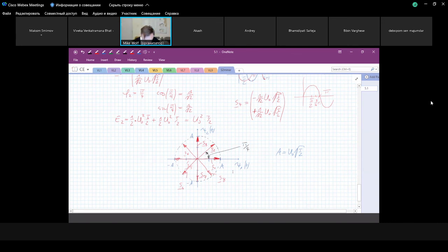This is, of course, the next topic, modulation schemes, but this is the signal space of 8 phase shifting. A modulation scheme where we shift the phase depending on the symbols to be transmitted. And we have 8 different levels for this phase. Of course, the signal energies are all the same: E_i is equal to u0 squared times T by 2 for all i. And then we stop. That's all.